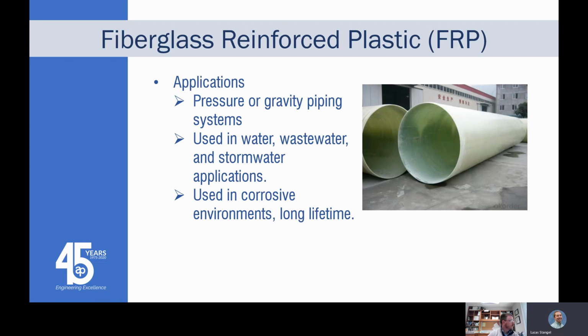All right, I'll talk real quick about fiberglass pipe. Most of the guys on here probably haven't dealt with it or seen it too much. Lately, there's one company that's been trying to push it more in this region. I've been seeing it more on irrigation projects, where there are larger and longer runs, but it could be an option for your transmission lines as an alternative to HDPE like we've talked about, or if you have any really high pressure systems.